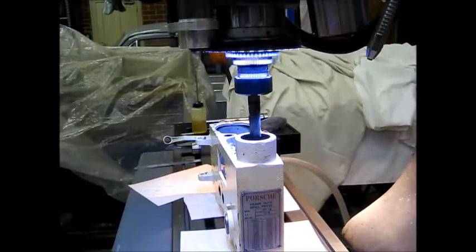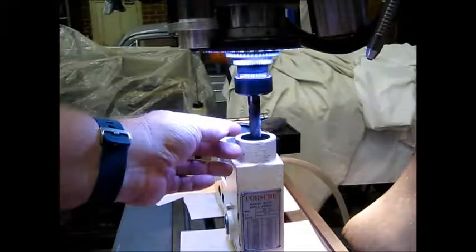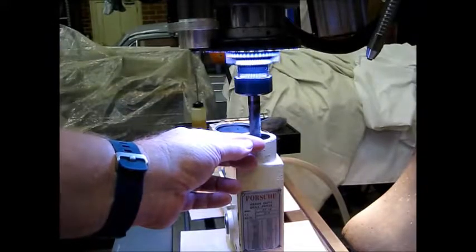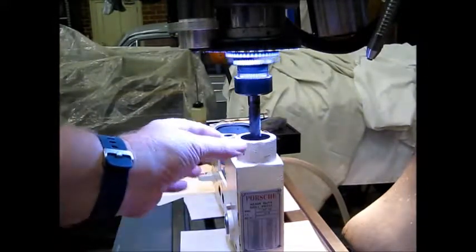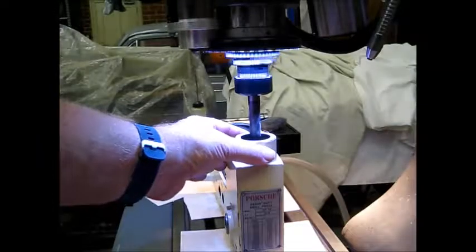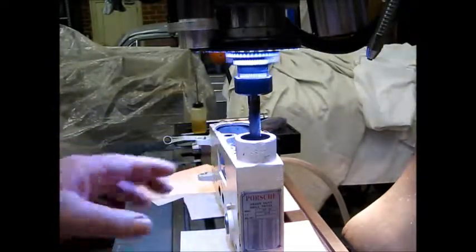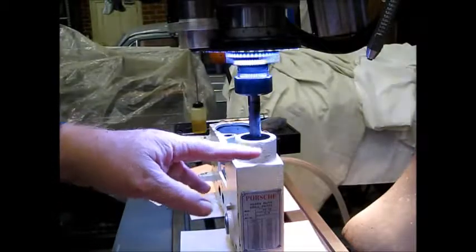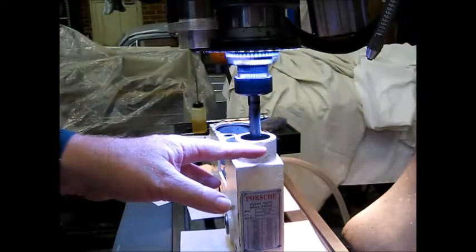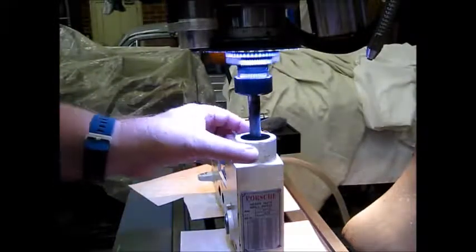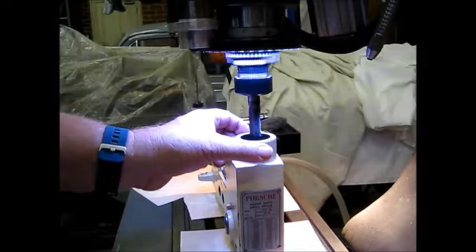The first instruction I'm going to type in is to move out this way in the X direction to plus 35, which we've got a nominal radius here of 27, and we've got a 16mm tool here, which 27 plus an extra radius of 8 should give a tool path around here at around 35mm radius.